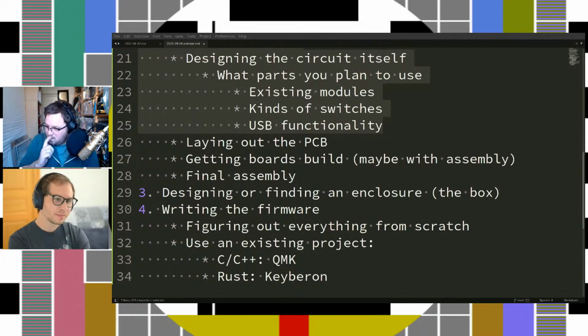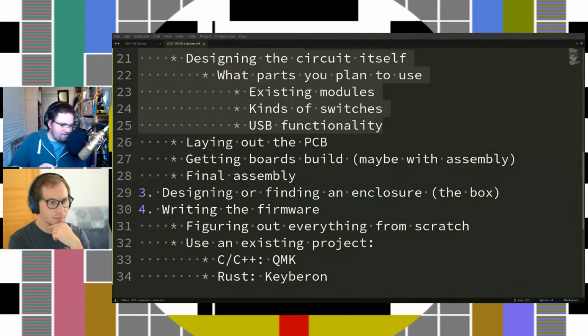Yeah. So there's that, and I'll mention that sometimes, especially for low volume stuff, cheating is good: going on Amazon and finding an existing 10 or 20 euro USB 3 hub that is relatively small and compact, and figuring out a way for the case where you can take the USB hub out of its case, so it's just a circuit board, bodge it on the inside of the case, or maybe flipped out where you have holes in the case where you can plug into the USB, and maybe do something tricky like solder the keyboard onto the back of the USB hub.